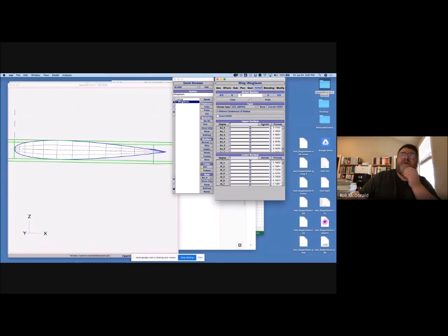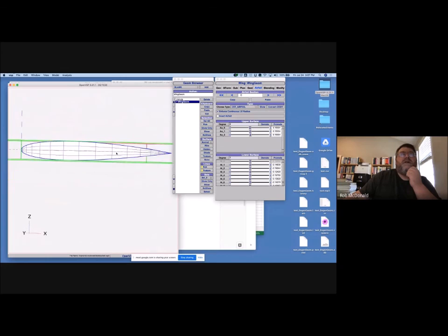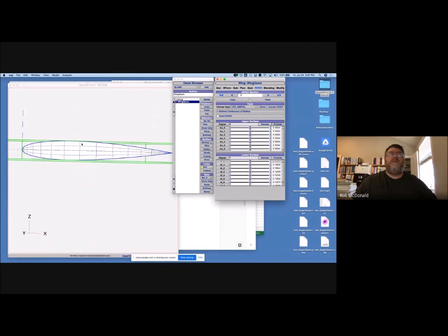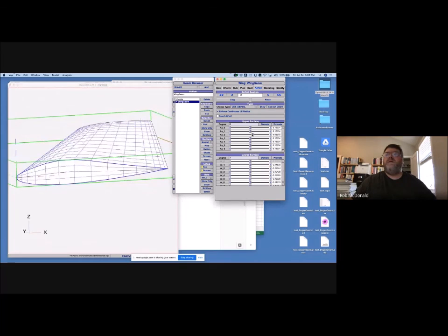Now, there's a couple of buttons here. You can say demote, and what we're going to do when we demote is take the 7th degree curve and come up with the best approximation of it with a 6th degree curve. So we go to 6th, and 5th, and 4th, and 3rd, and 2nd. And as we come down, you'll notice that the curve is not looking as good as it was originally. That's as low as we can go. It's subtle, but there are differences. And promote, well, this isn't updating. What's going on? No, it is.